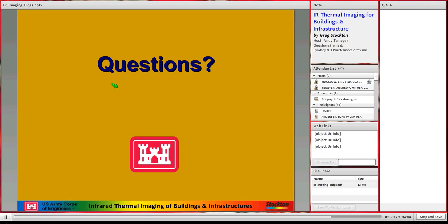Well, typically, there are two methods, and that document, the air tightness test protocol, explains how to pressurize the building using blower doors most of the time. But you can use the building controls. Basically, what you want to do is what we did at that hardware store. We stop the flow out of the building by putting it in full economizer and bringing the air in, but not letting it come back out. And the only place the air could go was out the leaks. So that's a pretty simple operation. I know in some buildings it's not. I remember when we were doing testing at some VA hospitals.